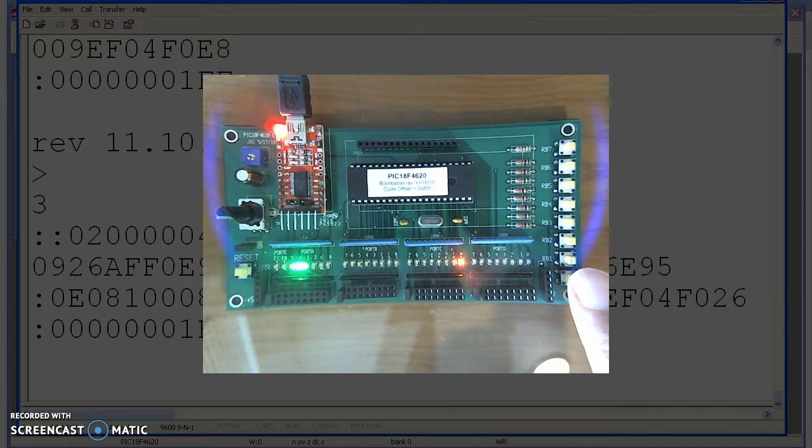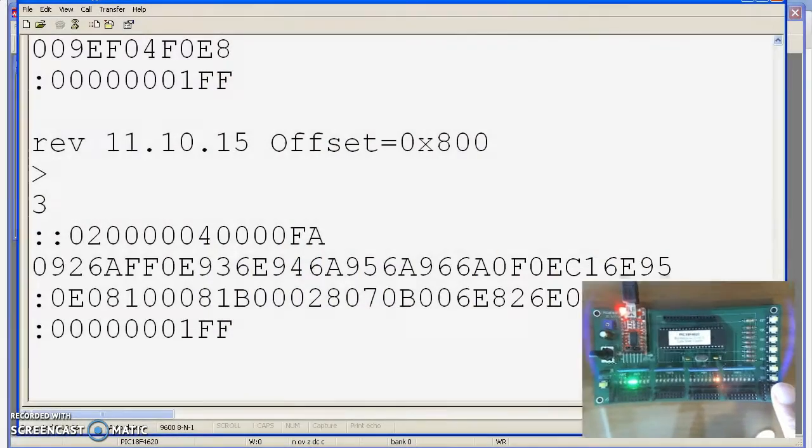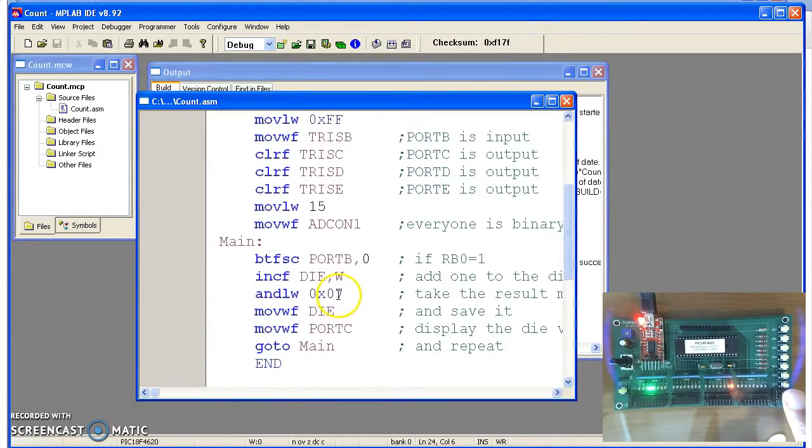This is one way to generate a random number on a PIC. Note that if the number I'm generating is a power of 2, such as an 8-sided die, it's fairly easy. If I want to have a number 0 through 7, just AND it with 0x07. Anything AND 0 is 0, anything AND 1 is 1. Doing mod 8 is actually easy.